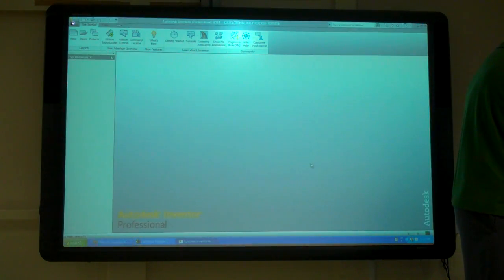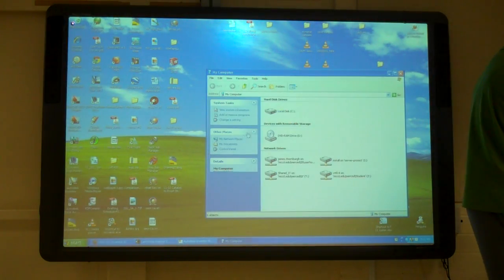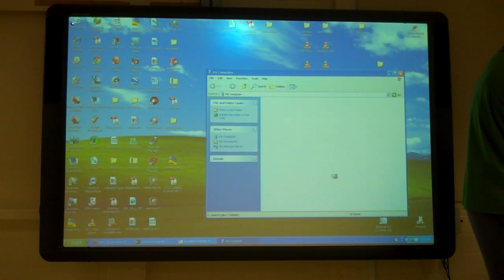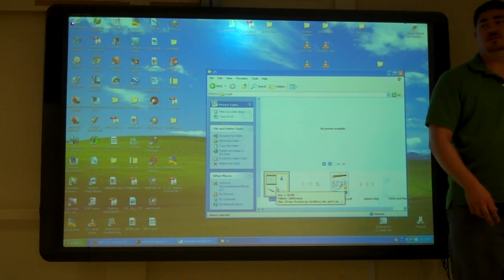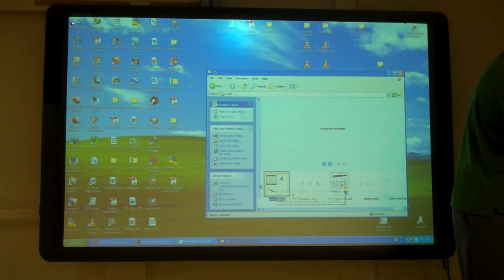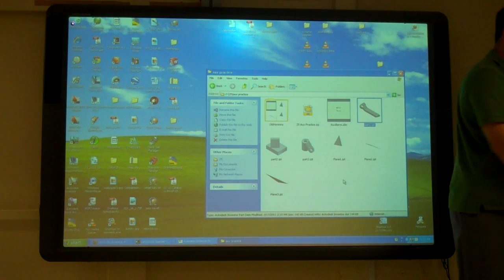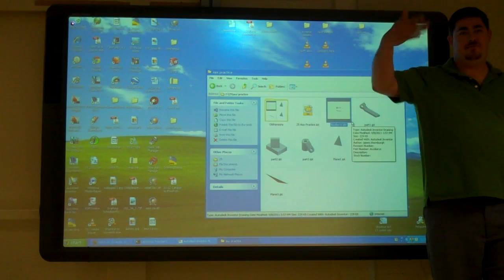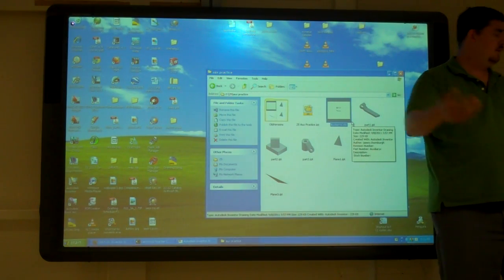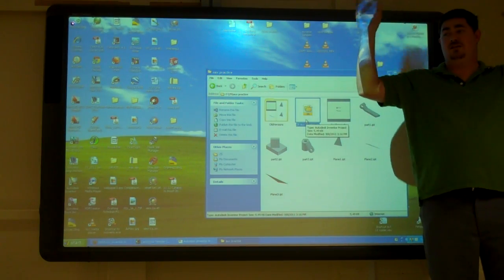So, if we go and look at the V40-4 drive and the 25 folder, we have a folder called Aux Practice. If I go look inside that folder, I see that I have a bunch of IPT files for all the different parts. I have an IDW, which is the drawing file that has the different pages of 2D views. And I have an IPJ file. That's the kind of the, hey, this is the folder that contains this project file.